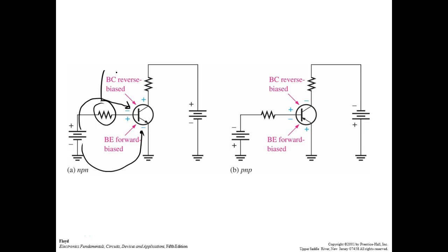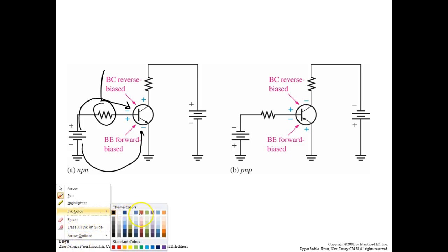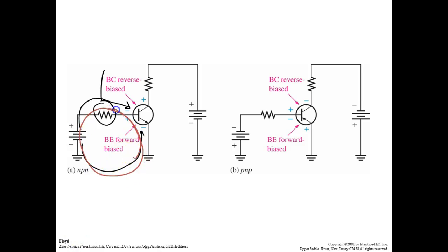So what happens is as soon as I do this, we start having current flow. So the current flow is in this direction right here, right? Everybody understand that? Now as soon as that forward bias is there, since this is an NPN, all these electrons spill into the base, and we don't have very many holes for them to combine within there. These electrons have a negative charge, and what does it see up here? It sees that big old positive charge sitting right there. Electrons are attracted to the positive, so 99.9% of the current flies up through there and goes around this loop right here.